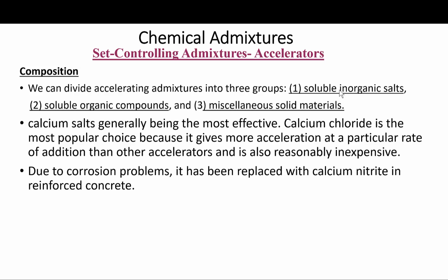The finely divided carbonates, like calcium or magnesium silicate minerals, are also reported to decrease setting time. So again, many products exist out there, and again, consult the people of experience with these admixtures. Make sure whatever is proposed fits the requirements of your job, and above all, make sure you comply with whatever specifications you are required to comply with. Testing and trial batches, that's all I can say.